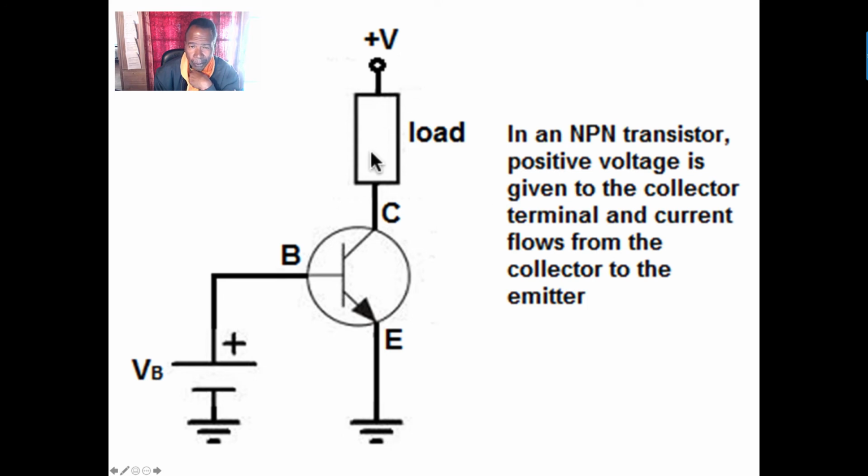So I've got voltage going to the coil like we showed you earlier, coming out of the coil. Remember, this is the coil. Use your imagination, this is the ignition coil. This is the positive side, and coming out of the coil is the negative side. So voltage goes into the positive side, through the coil, and out the negative side. The wire from the negative side goes into the module.